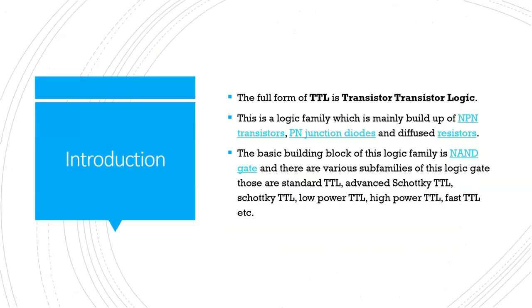First we will discuss what TTL is. TTL stands for Transistor Transistor Logic. This logic family is mainly built using NPN transistors, PN junction diodes, and some diffused transistor resistance. And the basic building block of this logic family is a NAND gate.